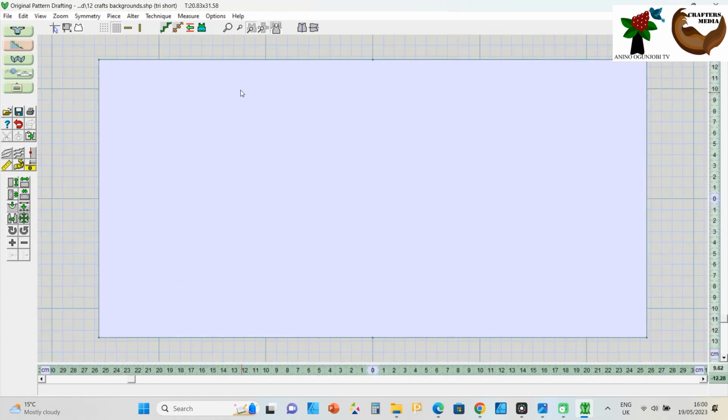and I'm going to centralize it because we are going to work on only this part. So come to this minus sign on the icons on the left. Click on the minus sign because we are going to delete some nodes. When you click on the node, make sure this vertical mirror is not there, because if it is, whatever we do on the left is going to affect the right. So make sure it's deactivated. If you find that what you are doing is affecting the right, then go back to this vertical mirror here and deactivate it. Undo your work, then go back there and deactivate.